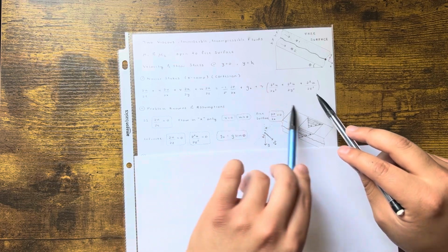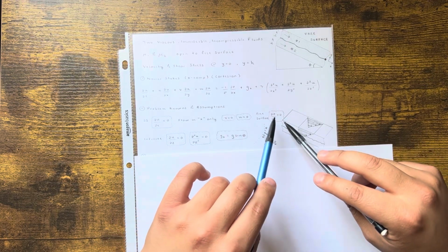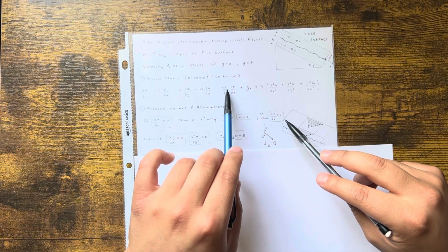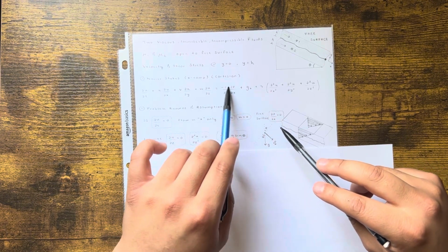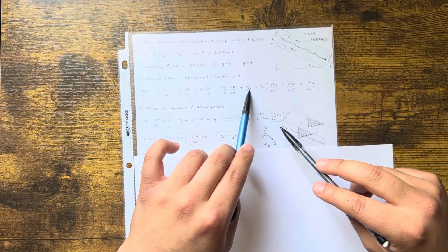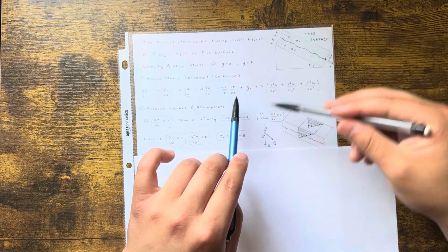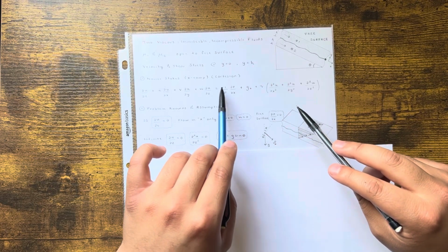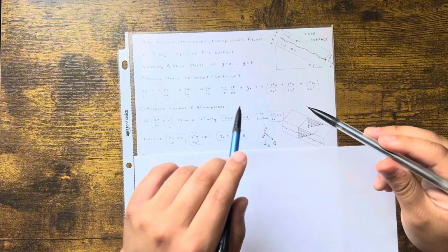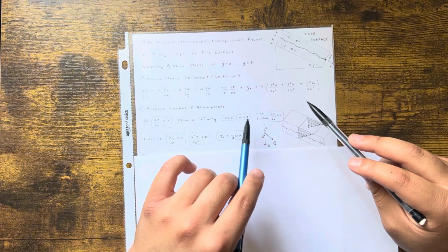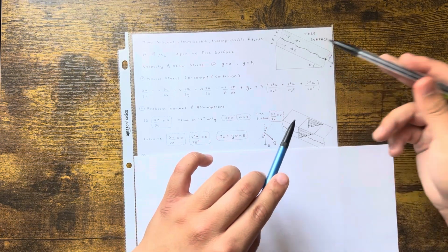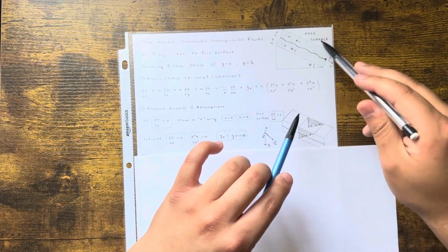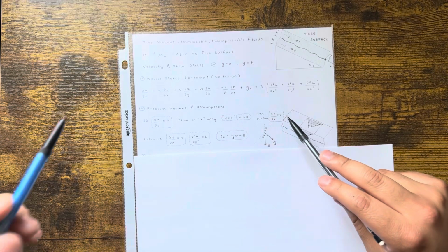And then we still have all this. Free surface, so there's no pressure gradient in the x direction. That's an assumption you should know when you're exposed to the free surface. So that is 0. Gx, and don't get me wrong, if you were doing it in the y direction, delta p over delta y would not be 0. This is along the x direction. There's no pressure pushing the fluid. It's just flowing, because it's exposed to the free surface. That takes time to think about, so just FYI. But in this case, you're exposed to the free surface, so that's 0.